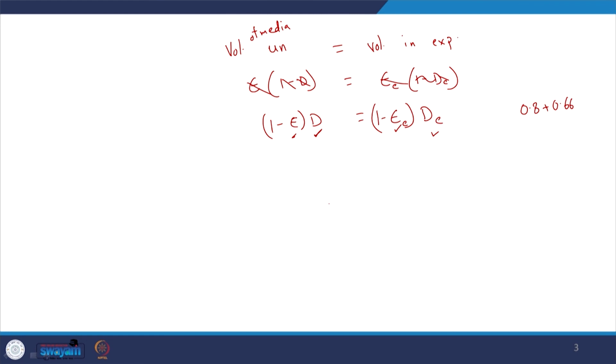So, once I get this porosity of the expanded bed, I can plug it into this equation, right. And I calculated Reynolds number, I calculated this Stokes velocity of settling, and then I will be able to get the backwash velocity. So, with that I will be done.